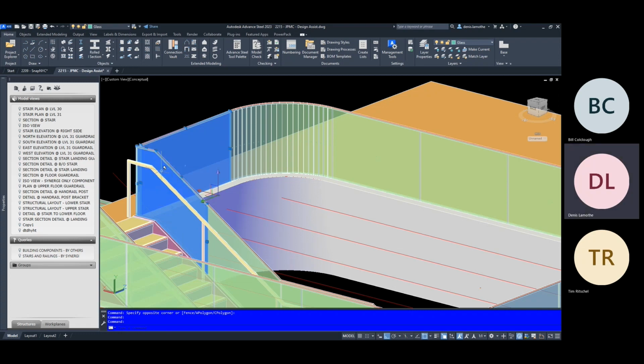We want to add an extra 1/2 inch to that height. The reason for that is that if the floor finish, say there's terrazzo being applied after the fact, and the subcontractor is very generous with the material and applies a lot more than what we expect, that's going to build up the floor higher.